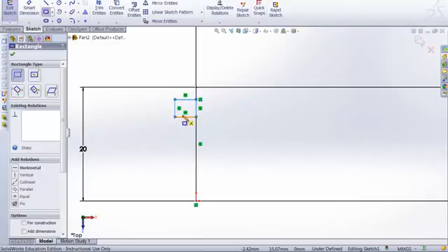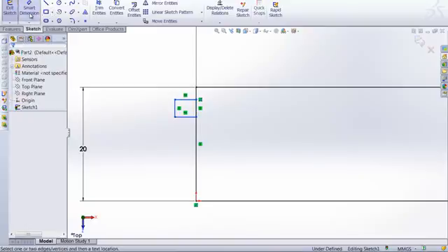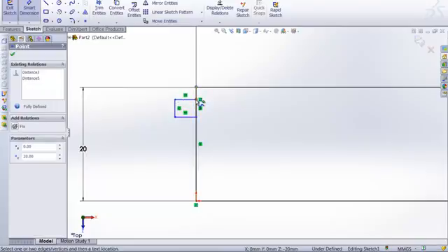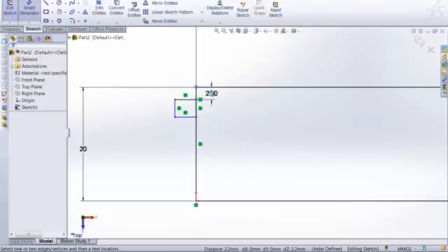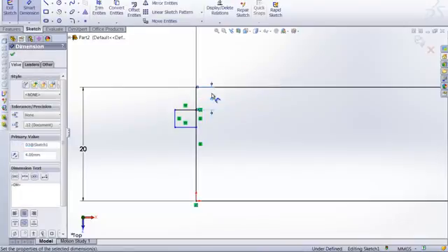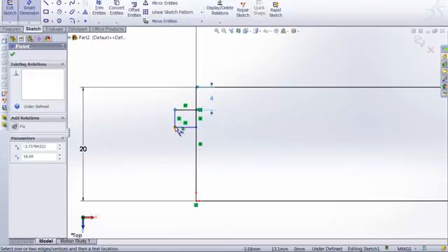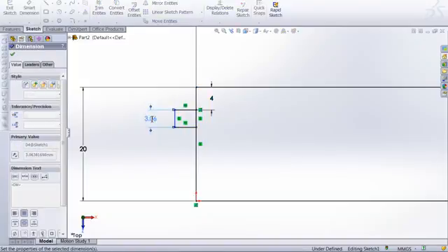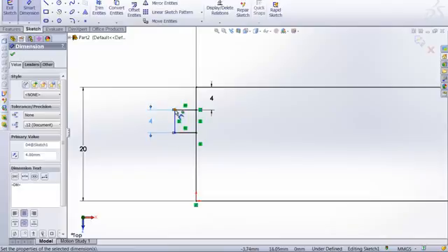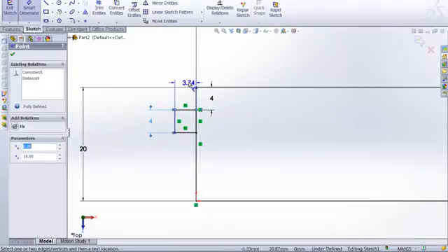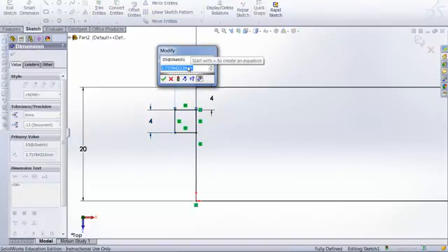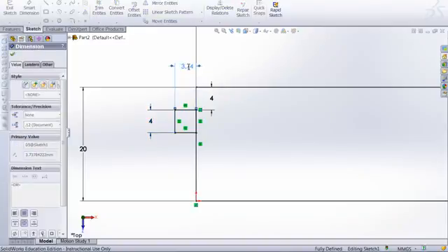That's the important thing. Start with here and draw. And now what we're going to do is to actually use the smart dimension tool. And we know that from this point, so clicking this point and click this point, and that needs to be 4. So we click once more and type 4. And we also know from this point, so click once, click again on this point, and then move to the left, click again. That is also 4 millimeter. I'm going to click on this one and at this point and move up here, click one more time on the number, and that is 3 millimeter.